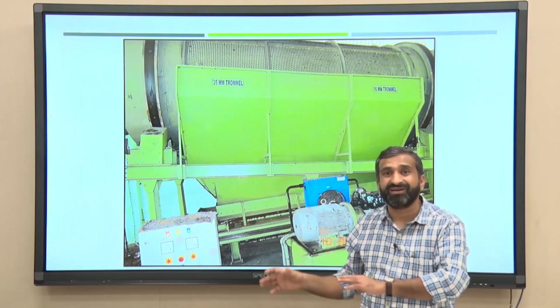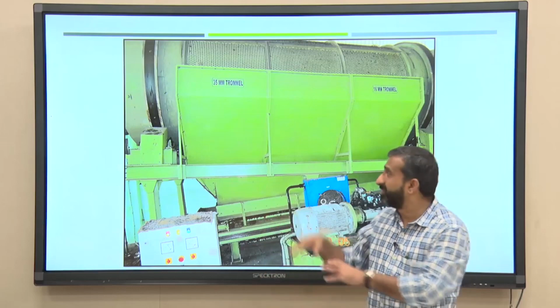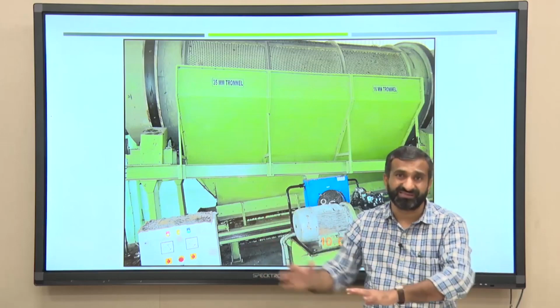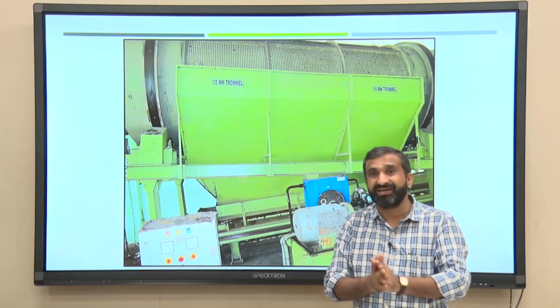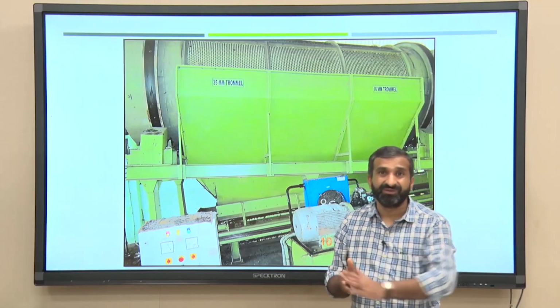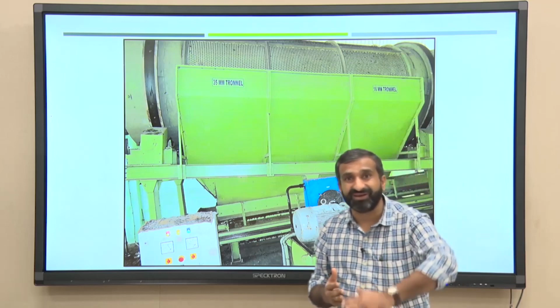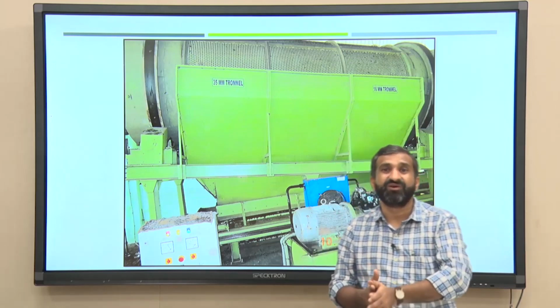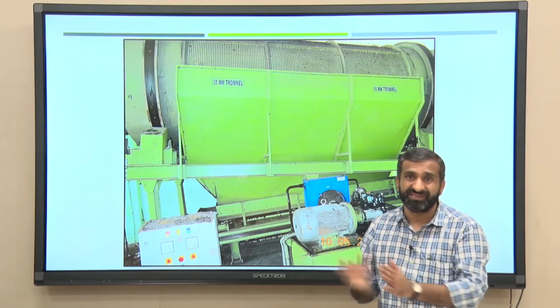So, filters will be required for that. Here filter means trommels. It is not that we can directly go for a 4 mm size filter, because it is very difficult to get the material filtered directly from a 4 mm sieve.